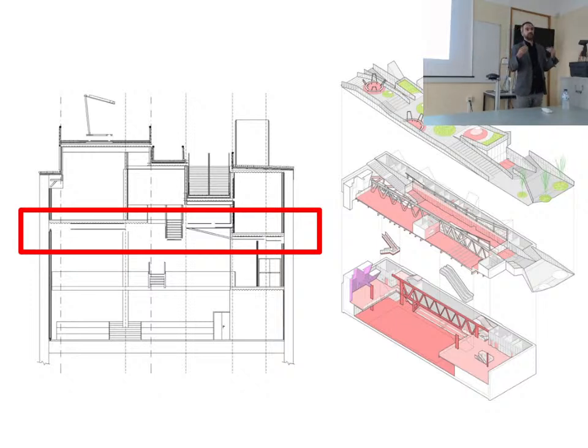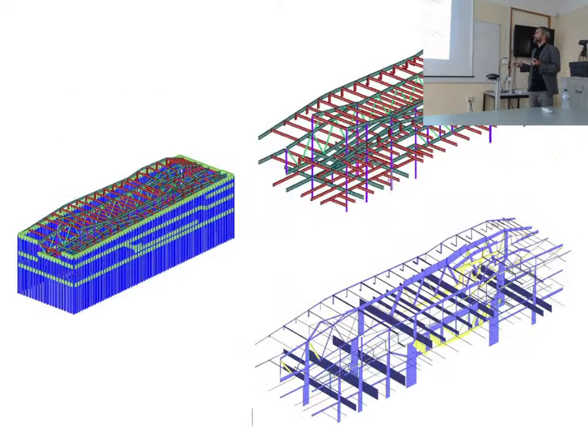This was the first issue we had, but the second one, the most important one, was the horizontal forces we have because of the building being below ground. And also because of the geometry, we have only one level, this intermediate level, that could be used as a path for these horizontal loads to connect from one side to the other, because at this level we don't have anything because of the basketball court, and at this other level, as you see, the geometry is not very favorable. So at the end of the day, we had to connect all the horizontal forces through this only intermediate level, considering also that it has quite a lot of big openings to let the light enter the building, and also for the stairs, elevators, and so on.